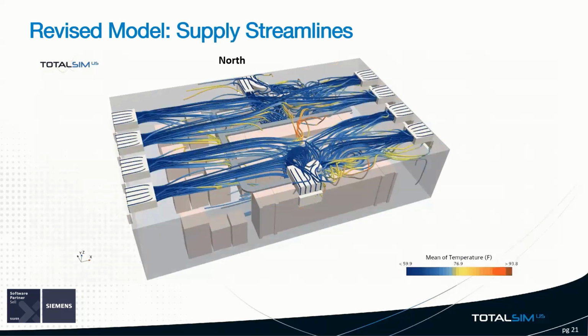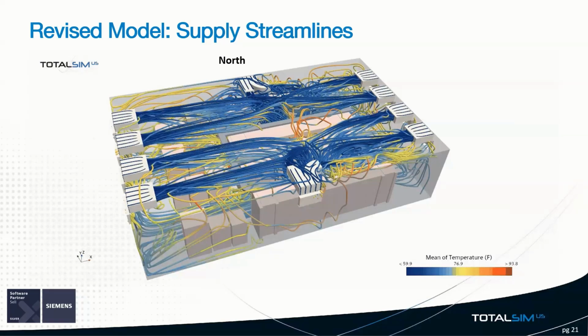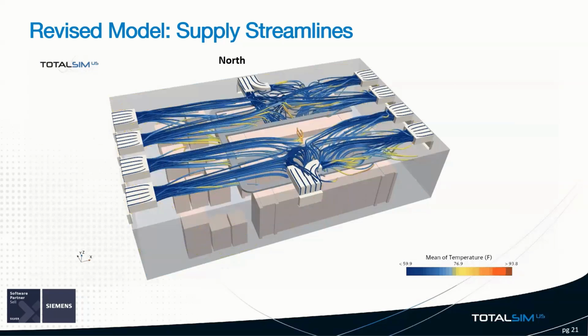This animation shows exactly what happened. Modifying the north and south units with bifurcated ducts weakened the airflow blowing north and south, therefore removing that air curtain effect. With weakened north-south flow, the second and third cooling system units on each side are pulled towards the north or south unit, leaving the middle of the room without proper cooling.